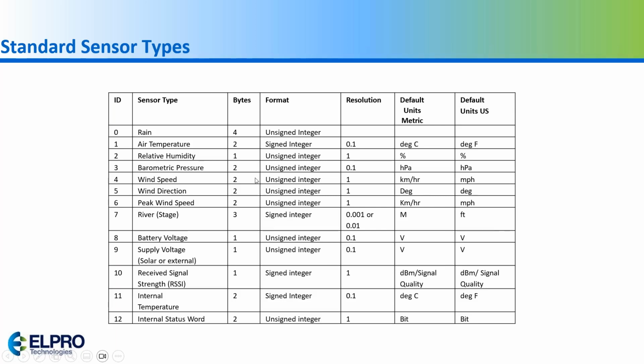As I mentioned before, of those 254 sensors, 13 of them are preset, but from 13 through 254, you can customize them. This is set up so that you have the sensor type, and you select that from the text line code that I showed you for configuration. You have different options, and per option you can determine the resolution, the scaling, or the units. For 13 through 254, you can do the same thing.